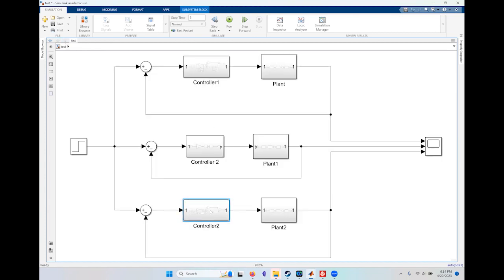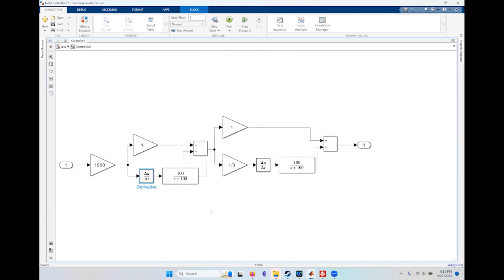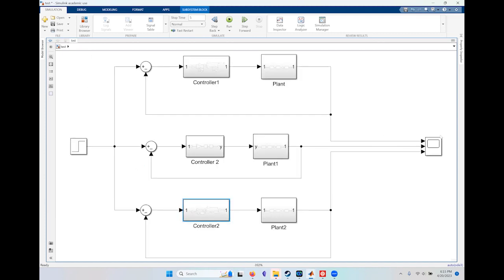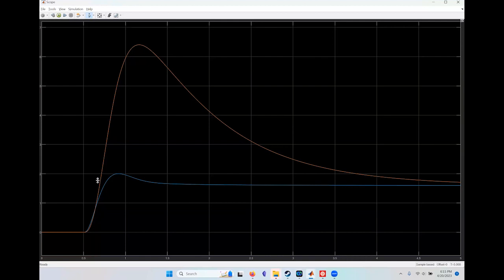The point is that whenever you're doing negative feedback simulation, avoid using this block, this derivative approximation, like the plague. It will absolutely give you an incorrect result. This is absolutely incorrect. No way around it.